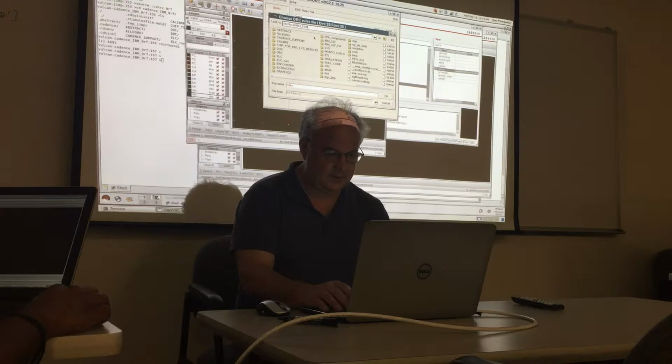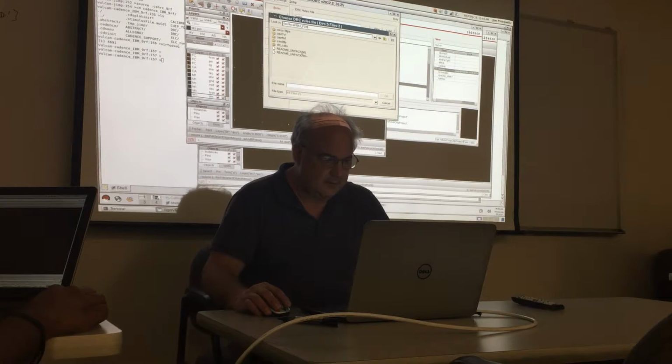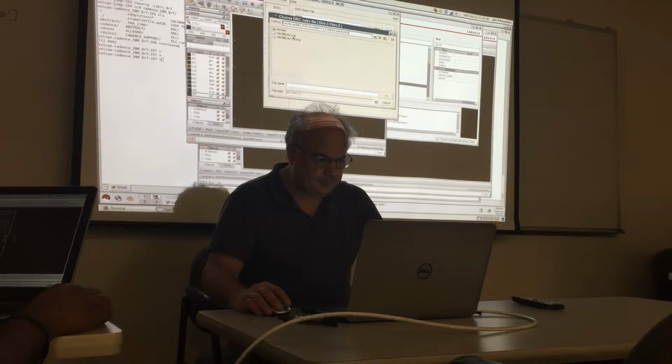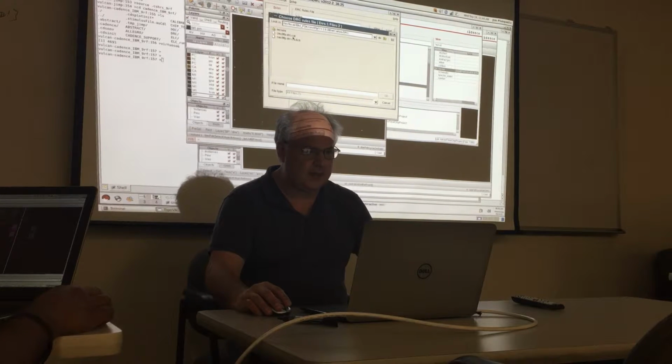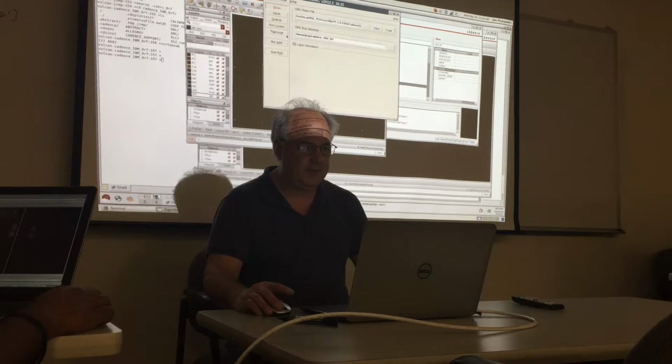And then I think you can hit enter and then just keep selecting it. So you can just navigate out there to Calibre, DRC, and then for DRC and LVS, there's only one file that you can choose, and as a backup here, just ignore it. Right, it's this drc.cal, which is the DRC deck for Calibre. So you click that, and then it turns green, and then it's going to be happy.